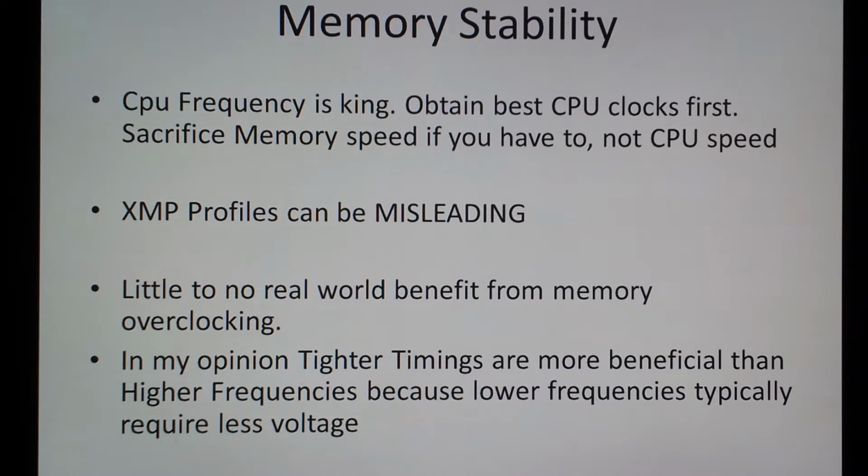In my opinion, tighter timings are more beneficial than higher frequencies, simply because higher frequencies tend to require higher voltages, and memory can be a very finicky item, even trying to run default parameters. So it is always a good idea to keep the memory voltage as low as possible.